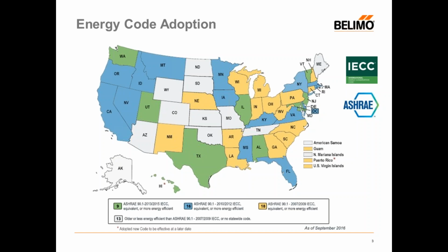What is integrated cooling? Integrated cooling is when economizing conditions are present, where temperature and enthalpy are below the high limits, and the first call, Y1, uses outdoor air to satisfy the cooling demand. If the load is not satisfied with 100% outdoor air, the thermostat will call for a second stage, and the economizer will begin to engage a compressor.